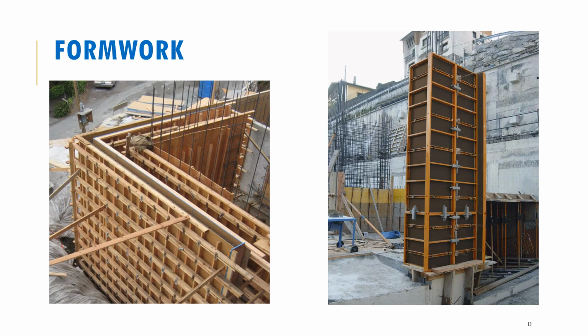So the first use, an obvious use that is very common in construction, is timber formwork, right? Remember how we said it's easy to vary the shape and size of your timber. And that's, of course, a reason why it's adopted for formwork.